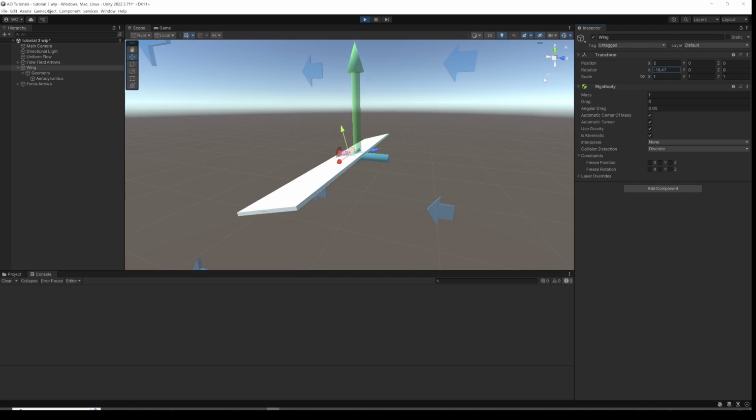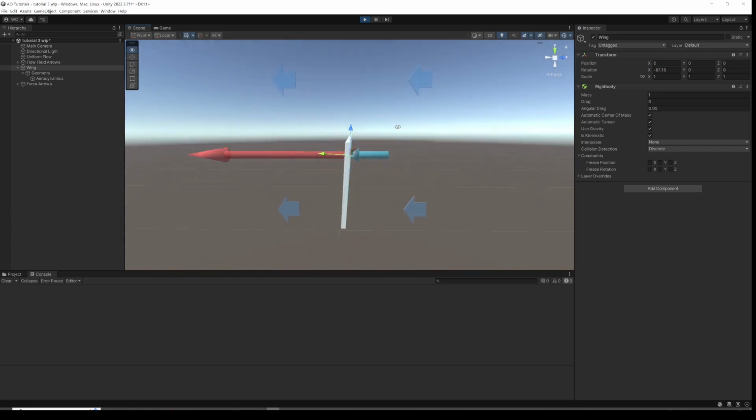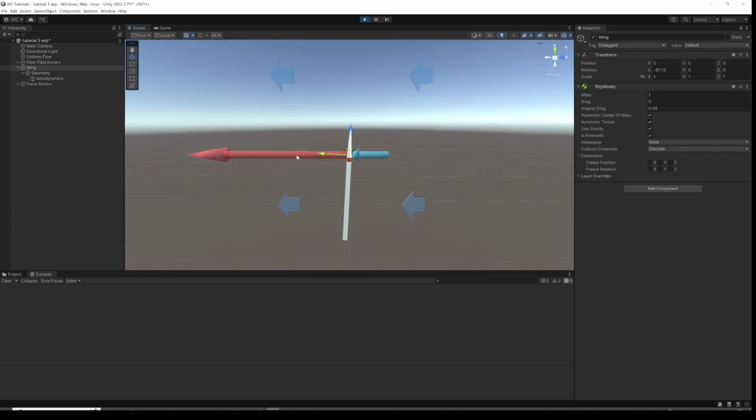What we saw there was that as you increase the angle, the lift goes up, but eventually you reach a stall, at which point the flow changes behavior over the wing and the lift drops off. As we go further up, we get less and less lift, but the drag is going up. And often when you stall a wing, the most concerning thing is not necessarily the loss of lift, it's the massive increase of drag. If we go all the way to around 90 degrees angle of attack, we've got no lift and lots of drag. And carry on round.